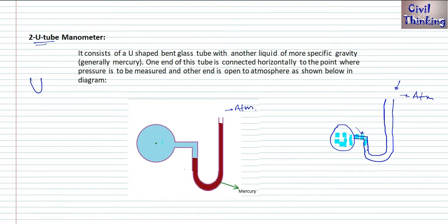That's why this is, because this is one type of fluid in this. When you cut the hole here, the water will come here. Now one thing is, in the U-tube manometer we have already another fluid. This fluid does not come from the pipe. We always use one heavier fluid, like mercury. It is a heavy fluid, right? We know the specific gravity of mercury is 13.6, by the way, and it is considered heavier, so we put one heavy fluid already in this.